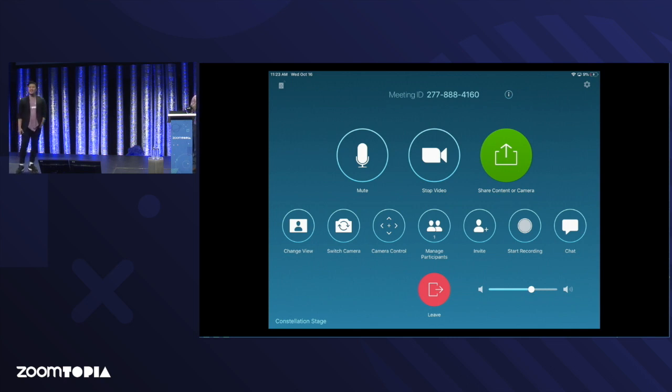Quick question for you. In the room controls, can you have a state indicator saying if it's on or off? There is no feedback in version 1. In version 1, it is output only. There are no inputs, and there's no feedback channel. If you're using a TCP connection, there's technically an accepted packet, but there is no acknowledgment from the projector after you send the power on command. We're not listening for any of that feedback.